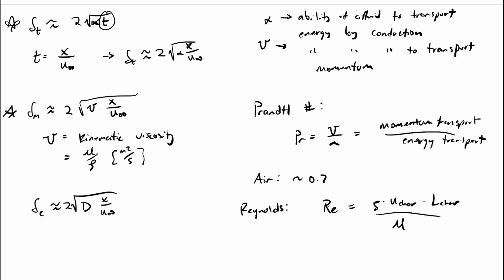So our job and the main complication for the Reynolds number is we have to decide what these characteristic velocities and lengths are. And that depends, so I write this in red, these depend on the geometry. These are things that are going to change based on your problem. If you have a flow inside a pipe, the characteristic length would be the hydraulic diameter. If you have a flow over a flat plate, the characteristic length is not going to be a diameter, it's going to be distance over the plate. So these are all going to change depending on the situation, but the Reynolds number is basically the same thing.